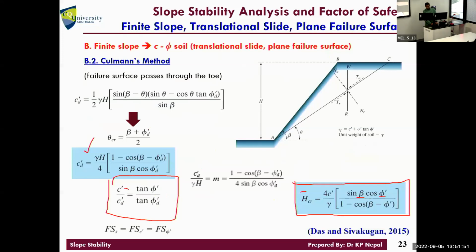Can you put that in? So if factor of safety is 1, okay, yeah, that's the trial and error, that's good. So if factor of safety is 1, CD must be C dash, yeah? So can you calculate that now? How much will phi D be, based on that, because the ratio is the same, right?